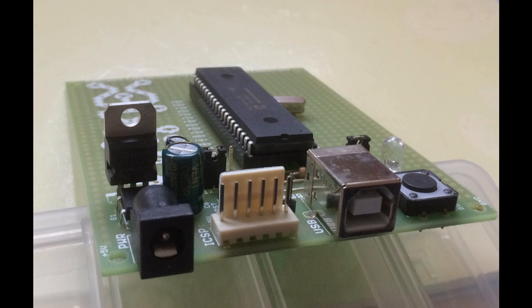If you are new to programming microcontrollers, I would recommend using one of these prototype boards which come with a configured power supply and an ICD connector for your programmer. The board used in this demonstration has a PIC 18F4550 microchip with a CCP output at pin 17 to control the motors.